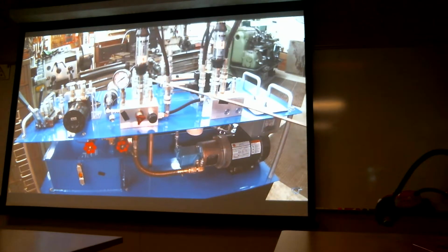So the only thing you see right here on the gauge is about 10 psi, and the reason you see that 10 psi is because it's taking that amount of back pressure to push that fluid through these fittings and through this block right here and make it go back through this filter into the tank. All right, so basically what I'm showing you is pumps don't pump pressure.